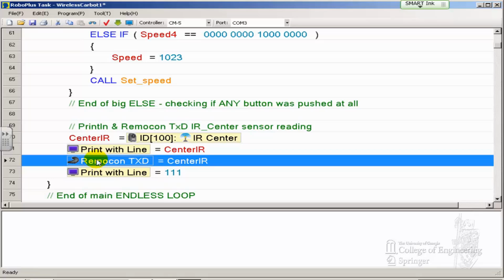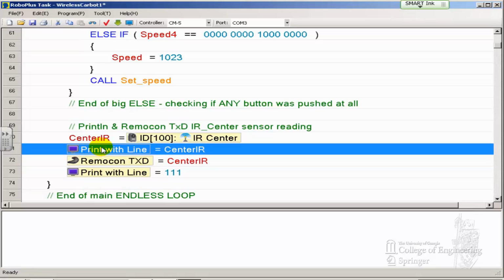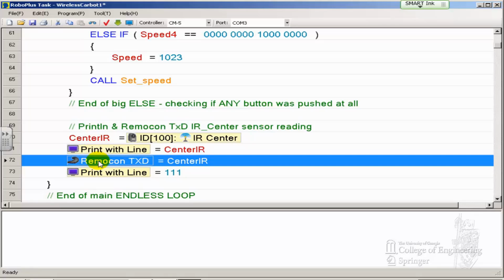And last time you remember what? When you print it, it basically just prints the data for send to IR. So remember in the output window, it printed out correctly because send only sends raw data, basically 1 byte pretty much. Basically, it sent out as RS-232 protocol. And the output window knows what to do with it. And then it printed out. But when you do TXD, you remember it's a ZigBee packet that it sent out, which has 6 bytes. So it has all kinds of things in there. So the output window says, what are you talking about here? So it printed the best it can.